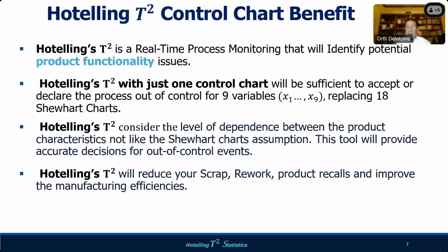So they hired a statistician, and the statistician conducted a deep investigation and found that the shafts used in those transmissions were made in the biggest diameter, close to the upper control limit, and the bushings were made close to the lower control limit, one in the upper and the other one in the lower side. So what happened with these transmissions running in use? With a little heat, the transmission gets tight, because the shafts and the bushings were in the opposite dimension.